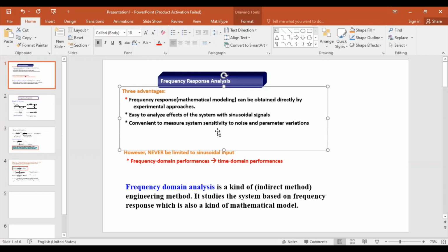If you decompose a noise signal carefully, you may end up with 5 to 10 signals. You may end up with 10 to 50 signals. But the frequency of all those signals will be very, very high. So a similar situation of noise can be experimented with by applying a very high frequency input to the RLC circuit. That's why, if you want to know how the RLC circuit behaves for a very high frequency signal or a signal similar to noise, frequency domain analysis will help you.